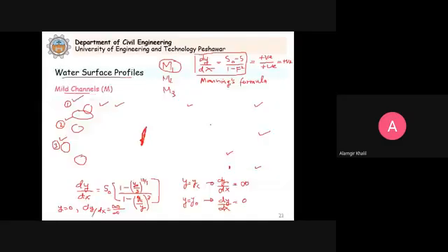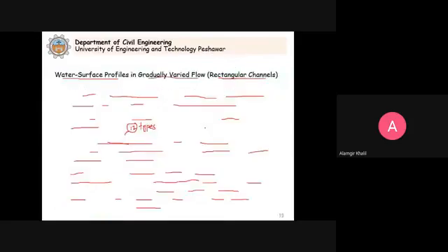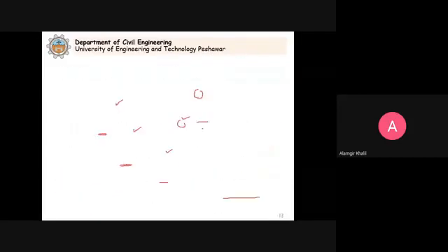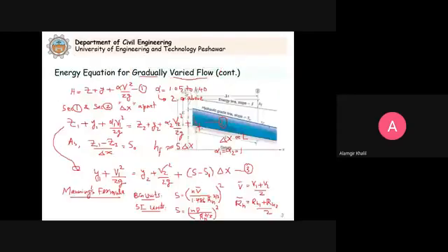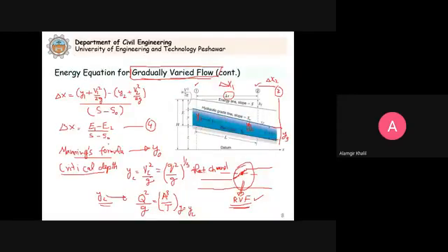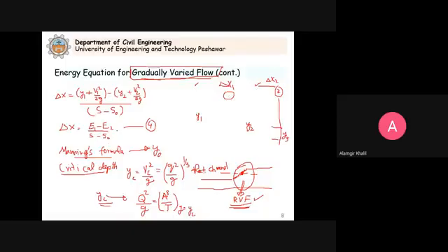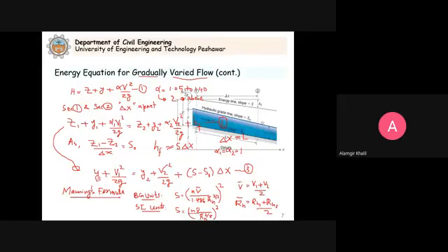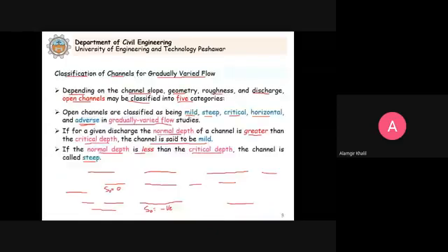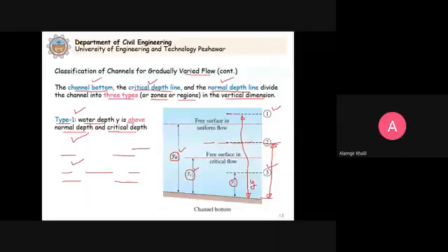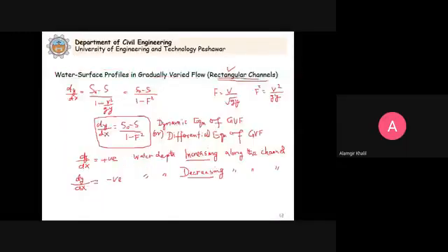And in this equation, we stated how this S is calculated, for the average conditions V bar and R_H bar, where V bar is (V1 plus V2) by 2, and R_H bar, the hydraulic radius, is (R_H1 plus R_H2) by 2 for the two sections. So that's why we say midpoint between the two sections, because we are averaging the conditions.